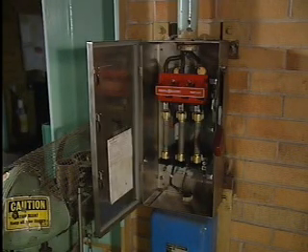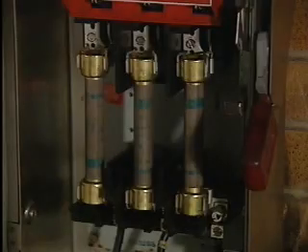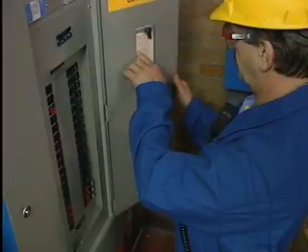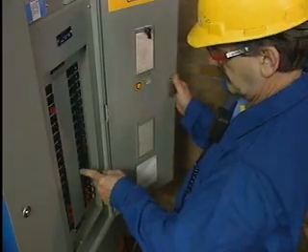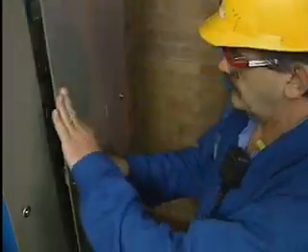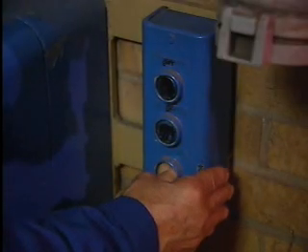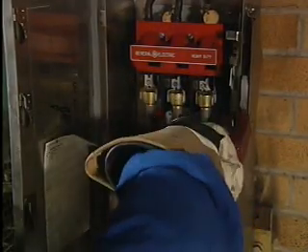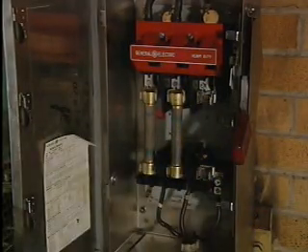Arcs can be caused by a number of conditions. One common cause of arcs is pulling out one end of a fuse that's carrying current. To prevent an arc from forming when a fuse is pulled, the current flow through the fuse should be stopped first. This can be done by turning off the power to the fuse or by turning off the equipment that's connected to the fuse. If there's no current flowing, an arc cannot form.